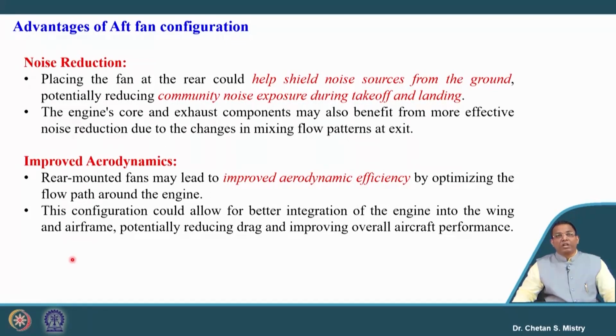It says rear mounting will give the aerodynamic efficiency, because we will be having optimization of the flow path. Okay. At the same time, when we are integrating that with the wing or airframe, that will be reducing the drag, and that will be improving the overall performance of the aircraft. So, here if we look carefully, we have installed this kind of engine on the aft side of the fuselage. So, you can say the placement of this engine is equally important, and the aerodynamicist needs to take care of this whole configuration.